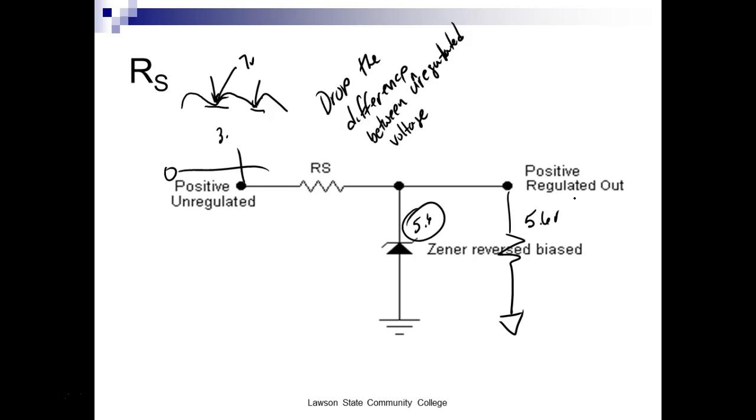That's all done. Well, I can't say all. You very seldom hear me say all because some engineer will come up with another method. Because we use Zeners for different things. We use them to eliminate voltage spikes. So I've seen Zeners hooked up back to back like this.